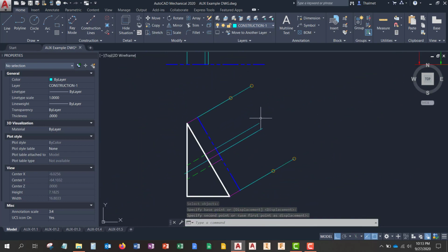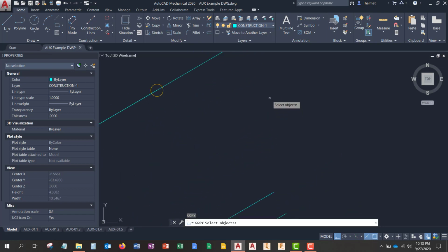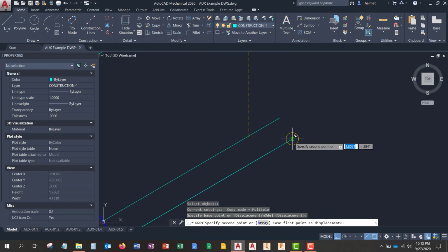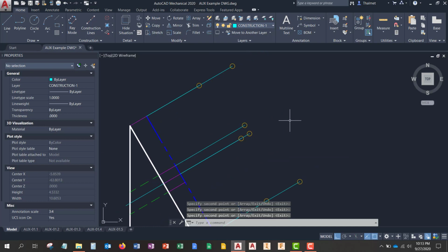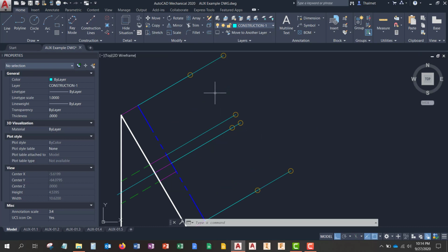Alright, now let's copy our reference points again, or reference circles, over to our different points. So if you notice here, we can make out the outline of our part now. We've also got the center point in our XY coordinates essentially, or the quadrants of that hole.